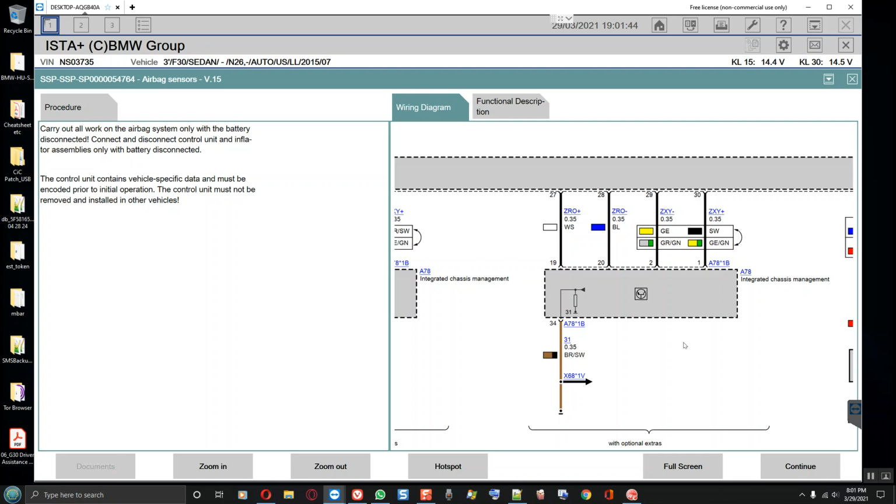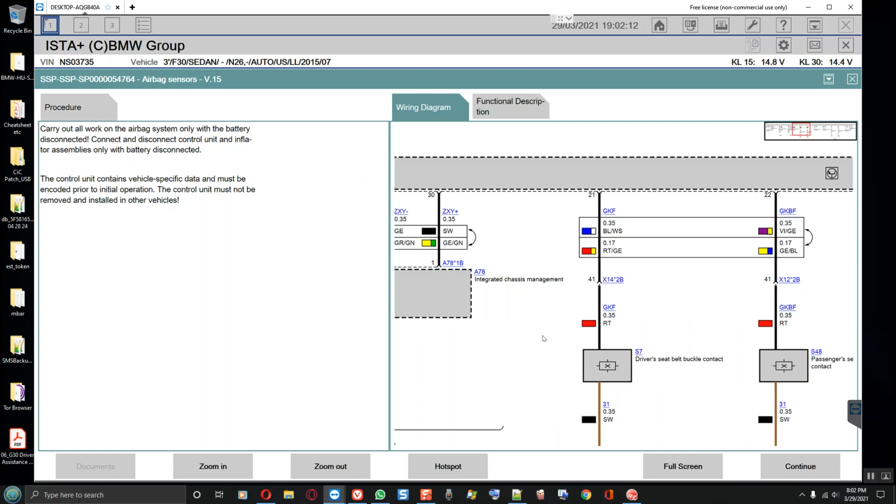If you want, you can run a new wiring on the same B plus wiring, and you can see if the fault goes away. You just need to see the signal on time as soon as terminal 15 turns on. The signal is not being carried across the wiring from the ICM to the ACM or back and forth in a timely manner, so that's why the fault code is set. So just pay attention to these things right here.